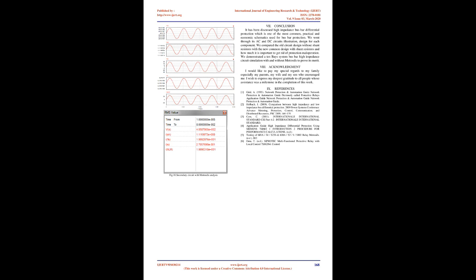Considering the complete circuit with Metrosils of type 802/600AS3/I, that have a maximum protection voltage Vmax equals 1435 V at maximum RMS fault current IFS equals 50 A. It is noticed that the RMS voltage across the relay, as per figure 11, is limited to around 405 V so that the relay system insulation can withstand.